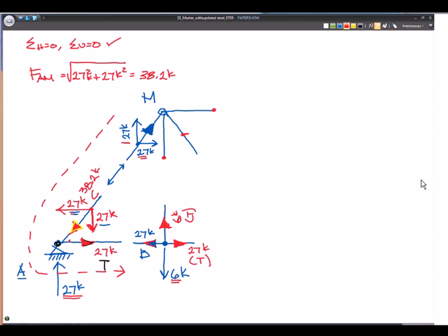Now that we know the vertical, member MB, now we can put that in as one of the unknowns up here at the top. So let's put this in blue. If that's 6 kips of tension, this is going to be 6 kips of tension.